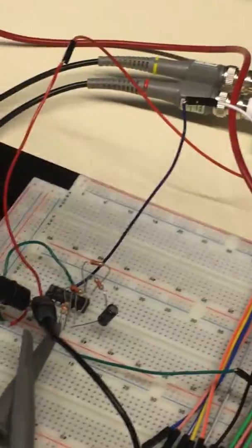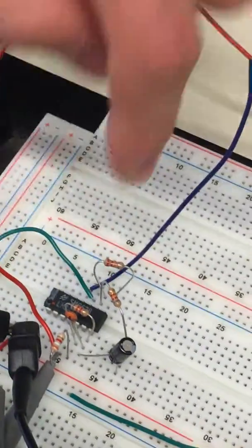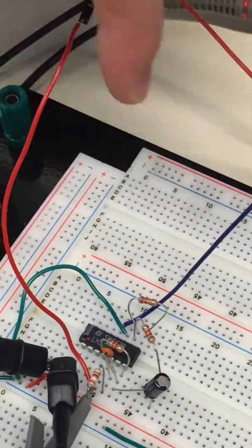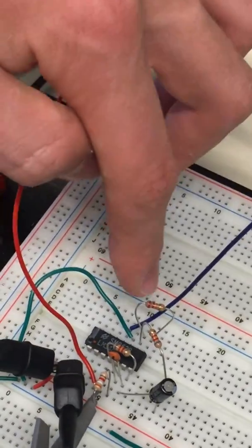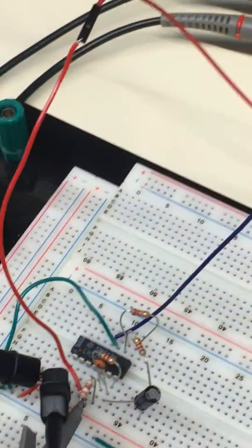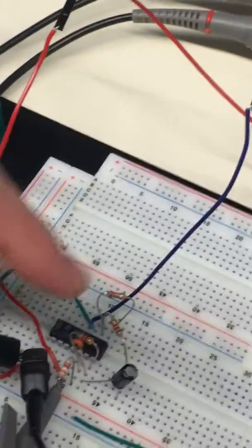So then for the high pass filter, we again have a capacitor. This time it's in front of the first resistor, and that resistor then is going into the negative terminal, and then another resistor is providing negative feedback with the output. And so that has this gain response.